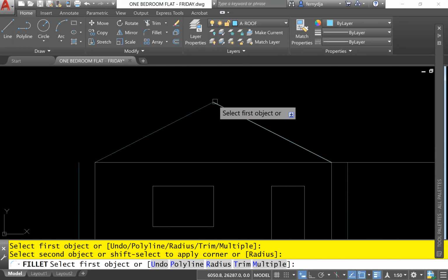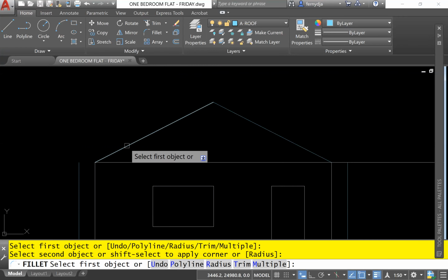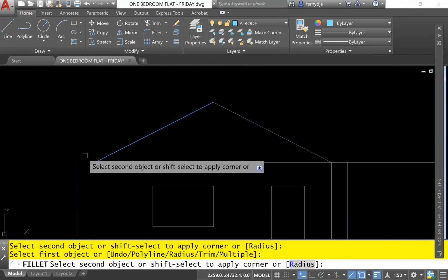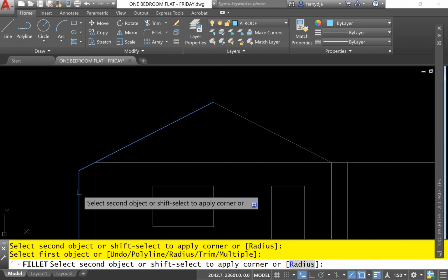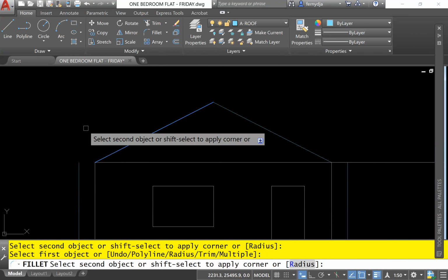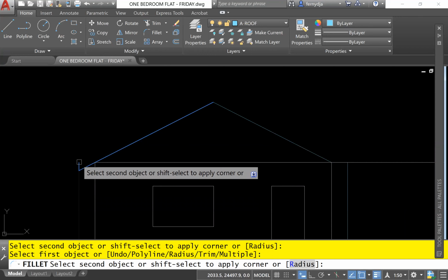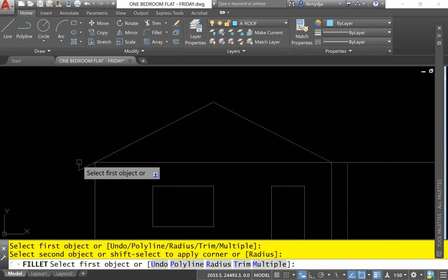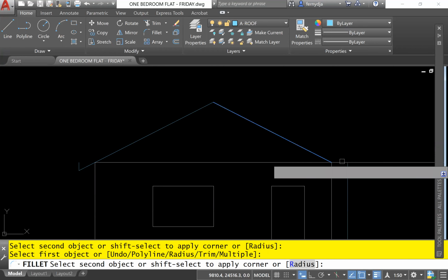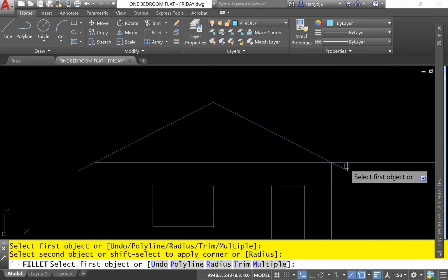at the top. However, I will do the same at the eave of the roof. So I'm going to click the slope line, but instead of clicking below, which will fillet down, we're going to click above where the intersection would be, and it will fillet up. So it does both at the same time. It extends and trims simultaneously. So I click on the other side, the same thing, slope line and vertical line close to the top. So basically we now have the overhang.